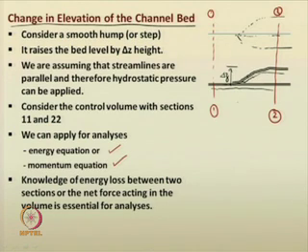That is, you can compare the energies at the two sections, or you can use the momentum equation for the entire control volume enclosed in these sections, so that the net forces in the control volume can be understood. If you use the energy equation, you need to understand what could be the energy loss between the two sections. If you are using the momentum equation, you should know the net force acting in the system. Based on those things, the flow will be occurring.